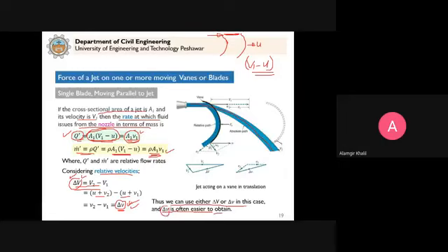This is the absolute path. So the velocity shown here is absolute velocity. You bring it here parallel to this to complete the triangle. So this velocity we slide here and bring it here to show the exit velocity triangle, correct?